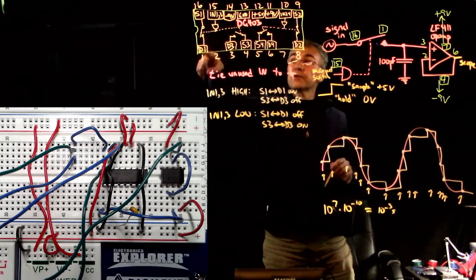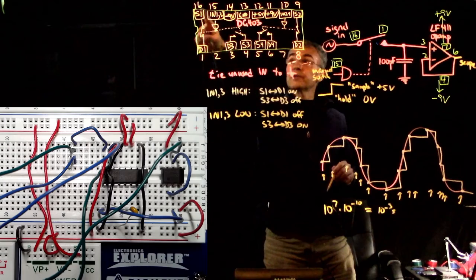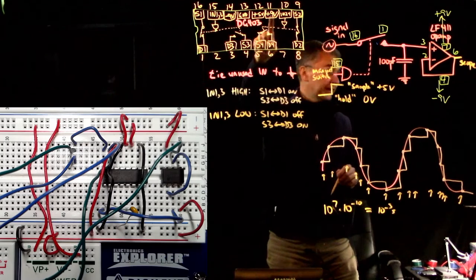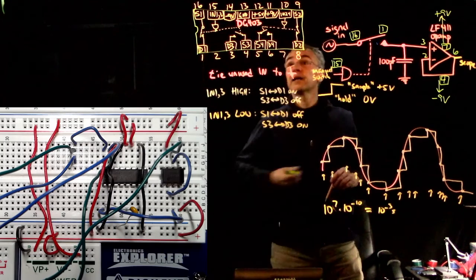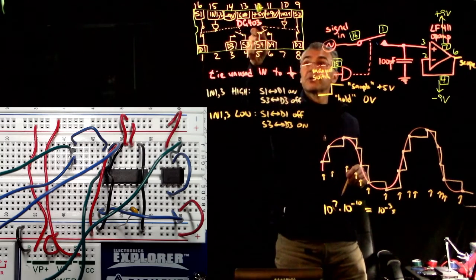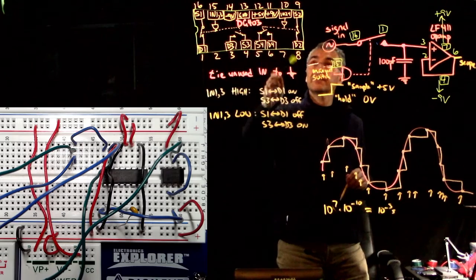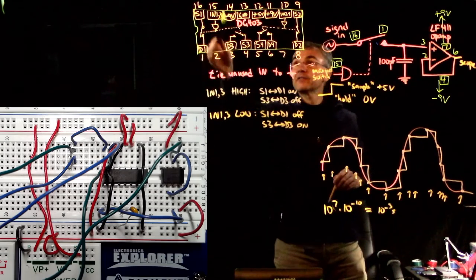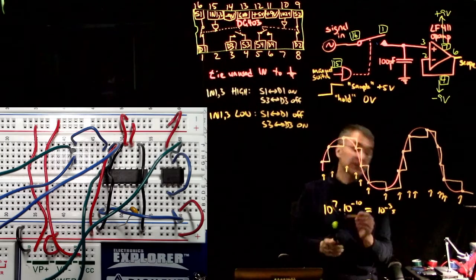Okay, so most of the action is pins 1, 15, and 16 here. So we have the powers, so minus 9, ground, plus 5, plus 9, on pins 14, 13, 12, 11. You want to remember to connect pin 10 to ground. It's an unused logic input. And then really the interesting stuff is 1, 15, and 16.